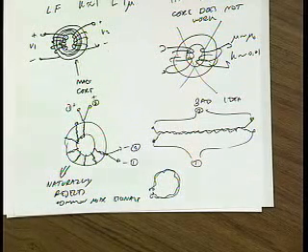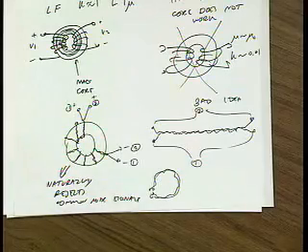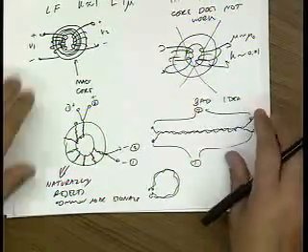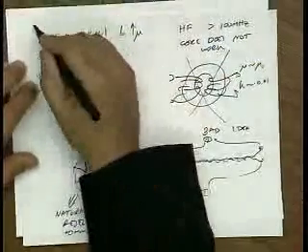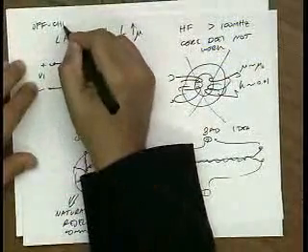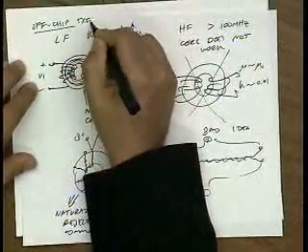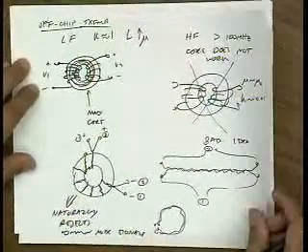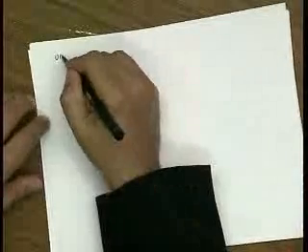From which material? You don't. Yeah, in CMOS technology, these are basically off-chip transformers, right? The way you build transformers on chip is very different. First of all, they're air core inductors. They actually use silicon or silicon dioxide, but these are non-magnetic materials, so effectively they're air core materials.